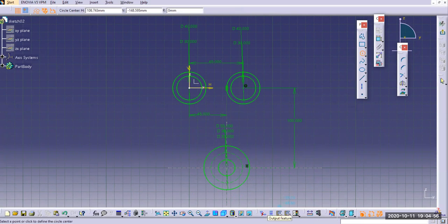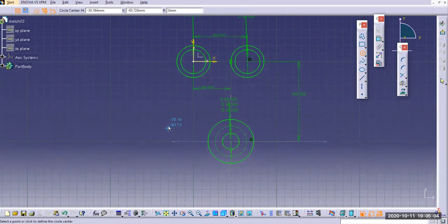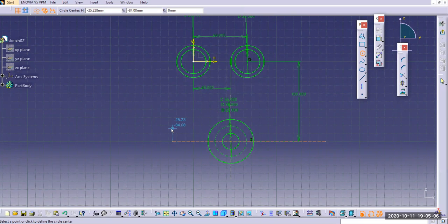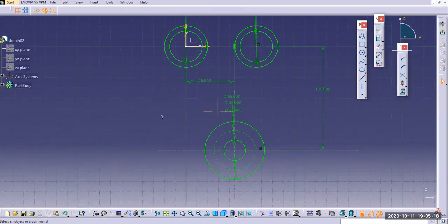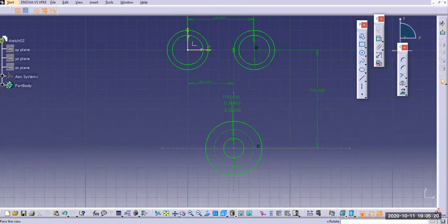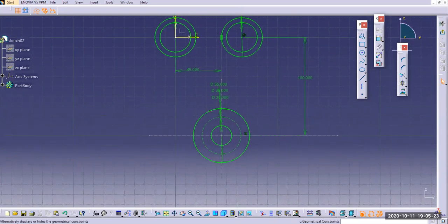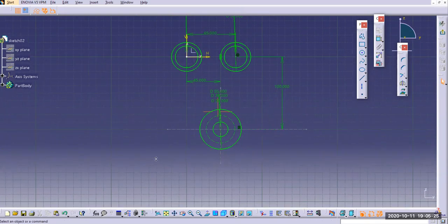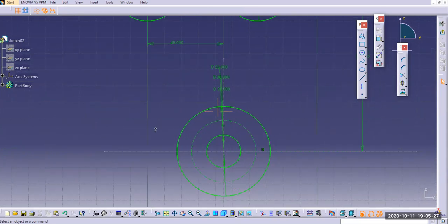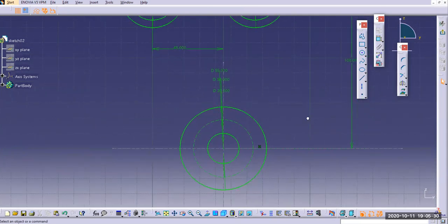So double click on this circle, and you see that orange line. So for now, we will just zoom in a little bit. For zoom, you click on shift, along with shift, you click on the mouse middle button. Let me show you. Sorry, control and mouse middle button. For zoom, control and mouse middle button. Yes, I hope you got that right.